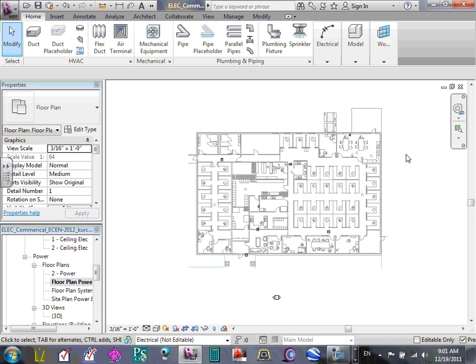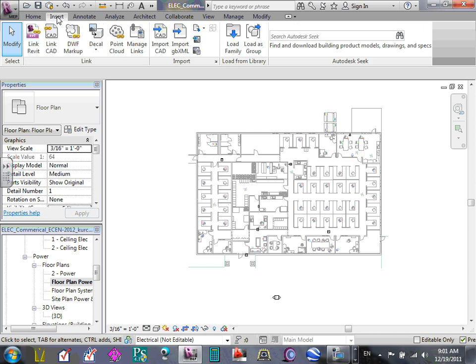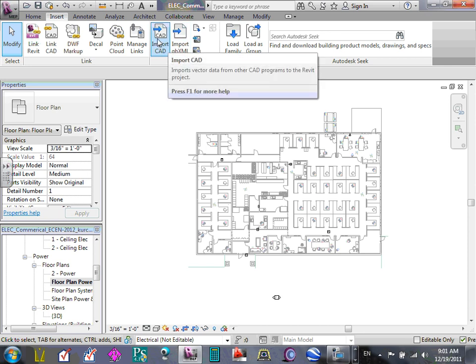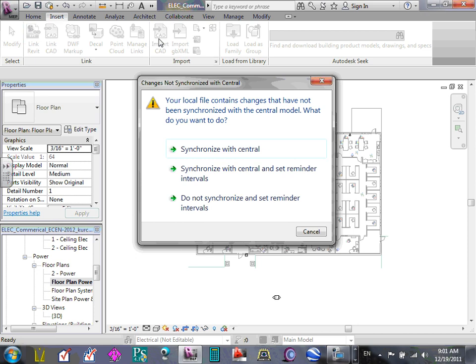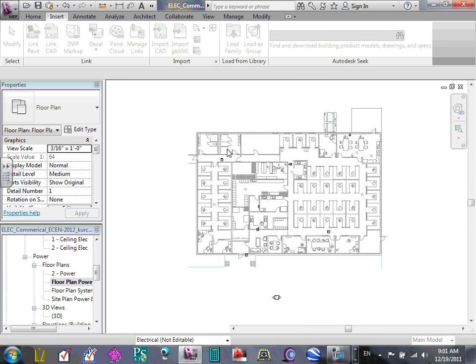by location in Revit? It's there. I couldn't get it to work, but here's how I want you guys to do one little thing. Ashley, go insert. So let's do it together. Go insert. Way at the top, insert. Import CAD. Everybody's insert, import CAD. Cool. Yep, import CAD. It says, do you want to synchronize with Central? I want to synchronize with Central.